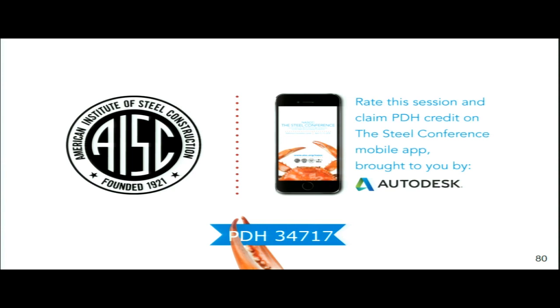About modeling the cladding system, I'm assuming we would just model it as dead load only and not actually model the cladding system as adding stiffness to the exterior line of the building, correct? Unless you were really confident that it actually added some actual stiffness to the exterior that could increase the stiffness of the spandrel, for instance. I've not seen a recommended modeling procedure for that. I would think that would be very conservative if you did that.